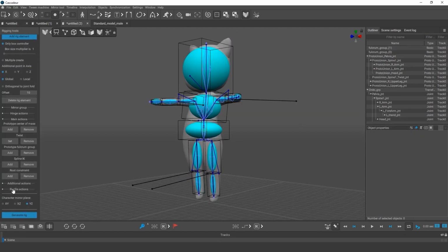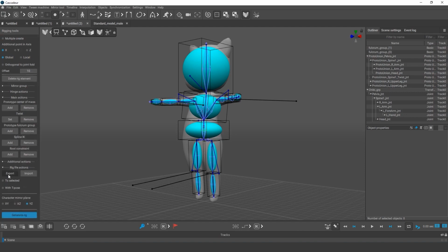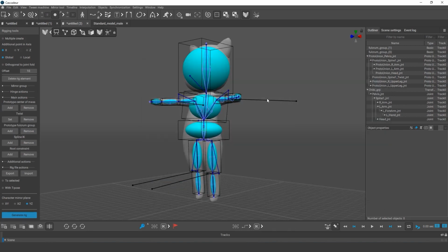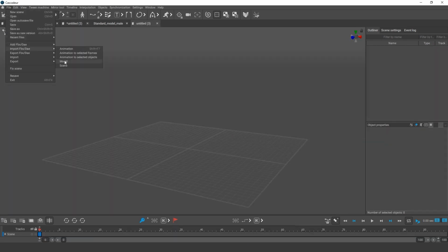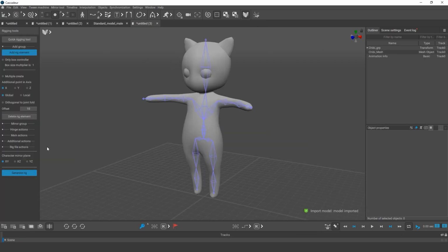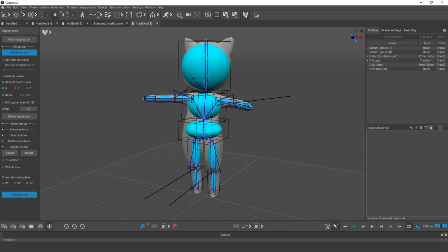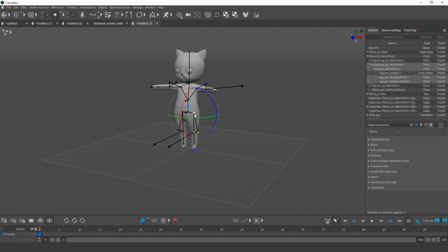And for the final important note, once you've finished creating rig elements, you can export your rig as a JSON file. Later you can use this JSON to quickly import the rig. The JSON file also stores the pose to which you've applied the elements of the rig, so don't alter the character's pose before you rig them.